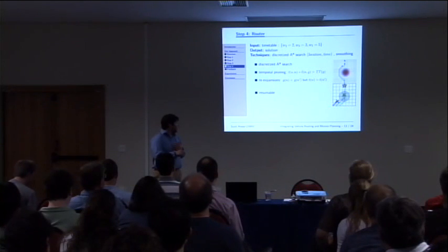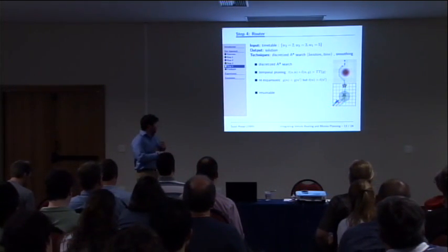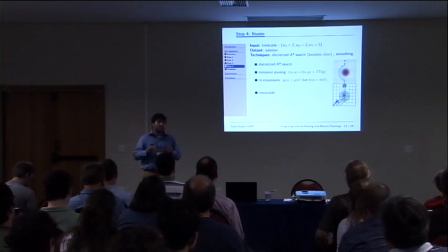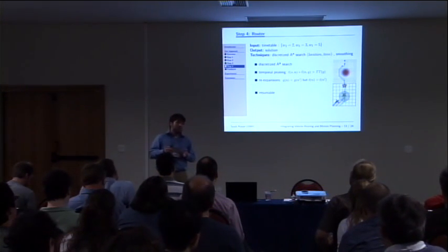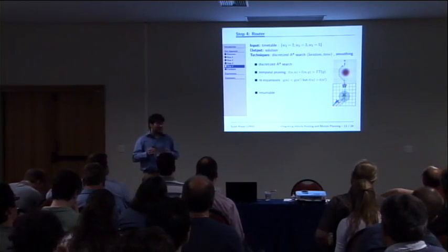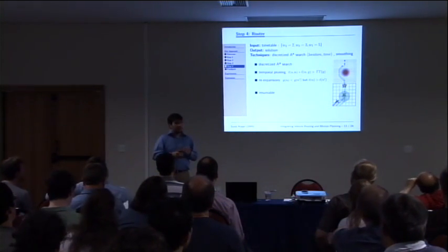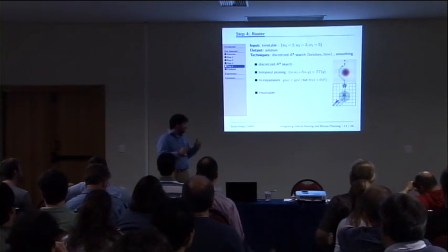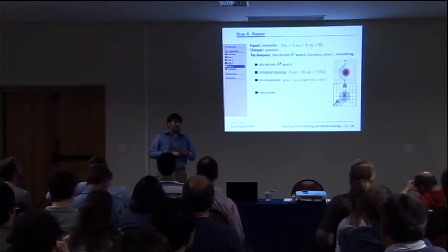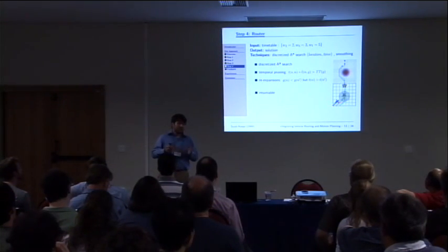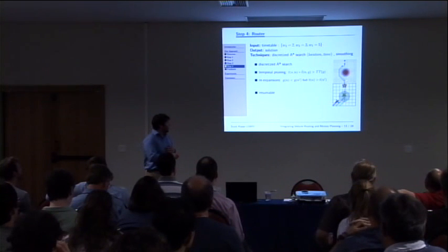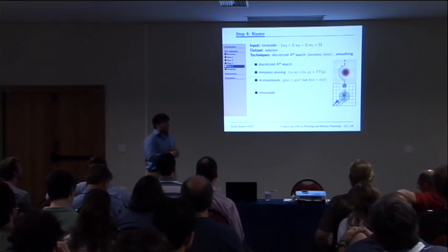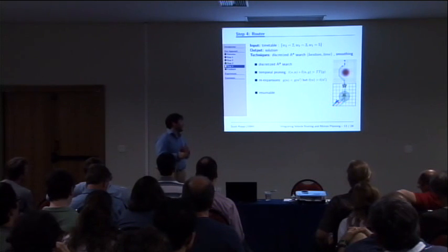As I said, in the discretized A-star search between the waypoints, we now have temporal pruning given the timetable. If the time from the start to the node we're currently at, plus an estimate of the time remaining, exceeds the timetable value that we were provided, we can just prune that search branch. Also, because of this pruning, we may need to re-expand nodes. More specifically, we may have to expand nodes that are more expensive so long as we arrive earlier at that node. Here we are avoiding cost in a very cheap way around the edge, but when we get to this point, we realize that the remaining path will be too long and we won't be able to achieve that waypoint in time.